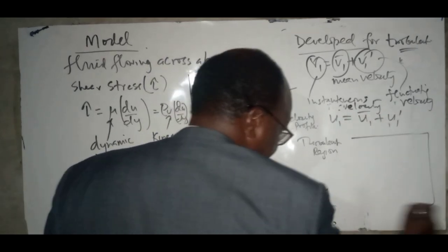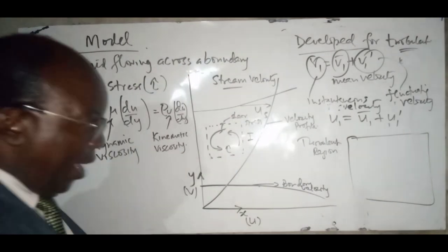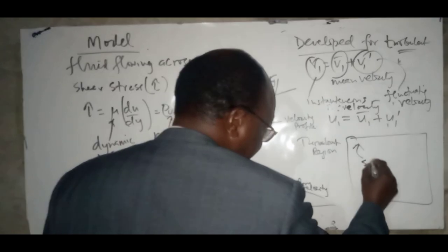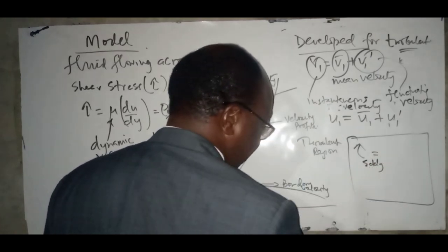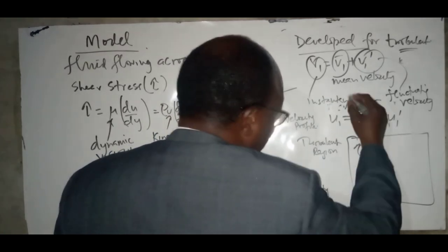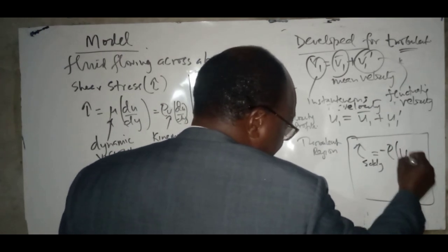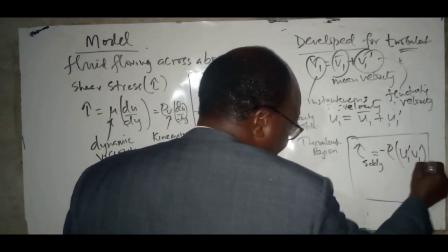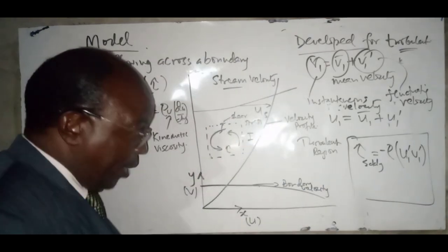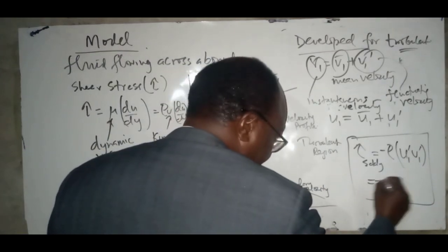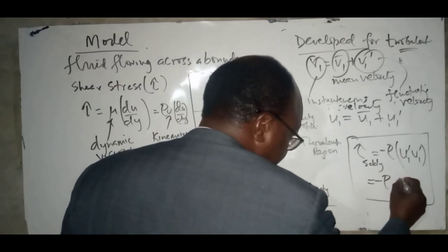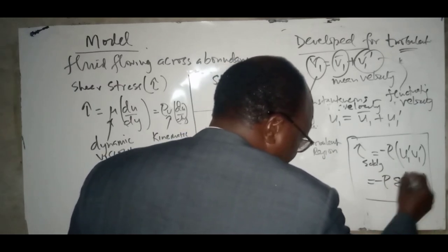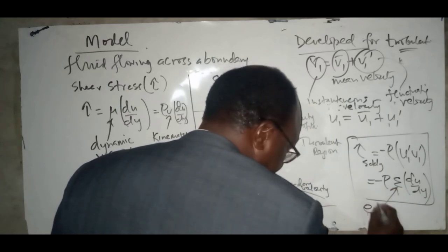And we ended up with the expression where we found that the eddy shear stress was the mean of these velocities which are fluctuating. And so we equated this and said that we could express it as rho E du dy, where this E was eddy diffusivity.